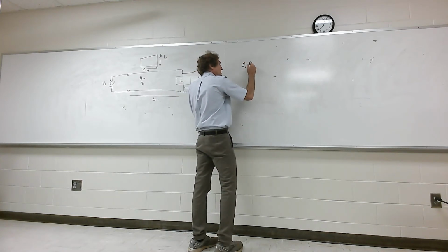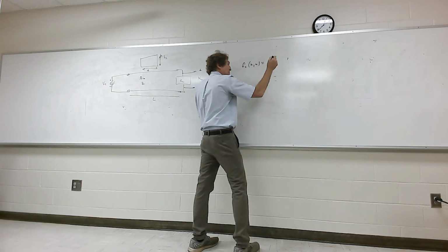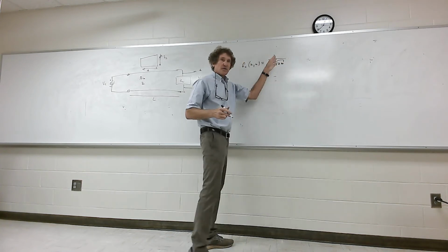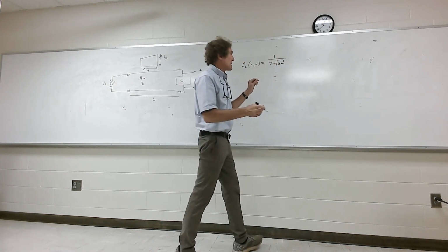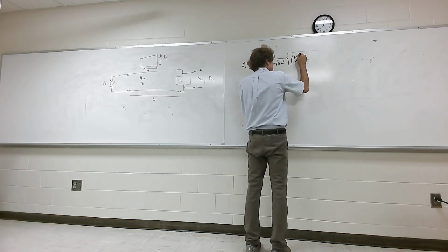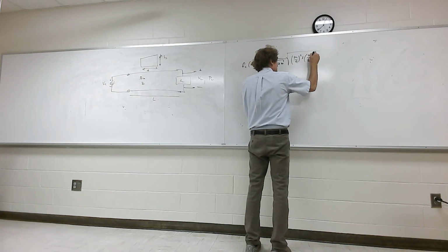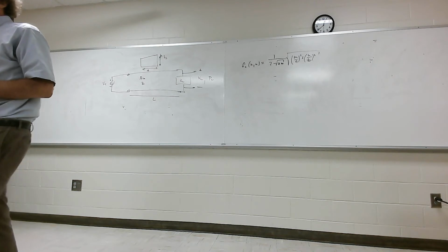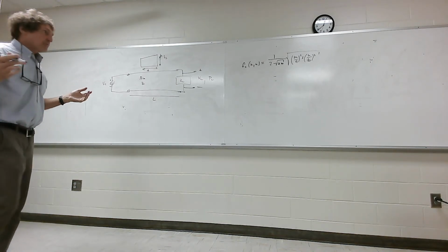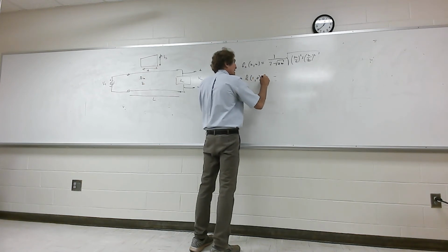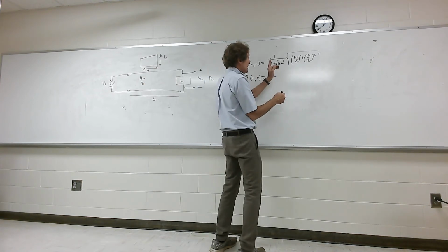And really, cutoff frequencies for the MN mode are what? Well, it's technically 1/2 square root of mu epsilon. We usually write that as just c/2, right? And then it's going to be times what? Square root of (m/a)² plus (n/b)², correct? Those are the cutoff frequencies for the different modes. The first thing we want to see is if anything propagates. So we get the fc10 mode.